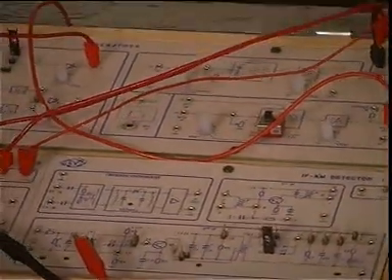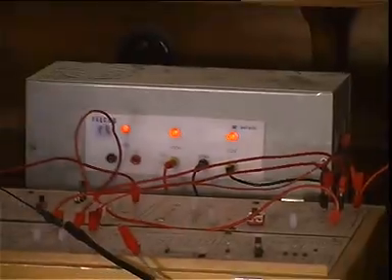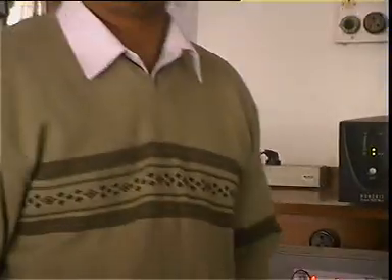For our demonstration, we will first measure the carrier frequency and the message signal frequency individually on the oscilloscope and then give them to the modulator. To carry out amplitude modulation, I require a carrier signal, a message signal and a modulator. So I will feed the carrier signal and the message signal into the modulator. At the output of the modulator I should get an amplitude modulated signal. Let us measure the individual signals on the oscilloscope, and then we will give them to the modulator and see how the output looks.